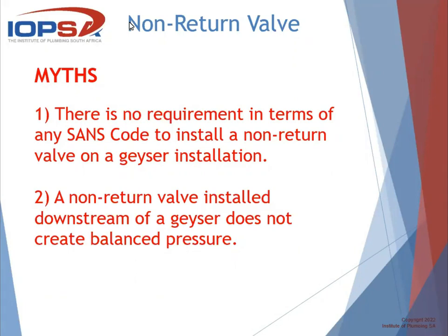So the pump must be able to overcome that non-return valve spring pressure during the day when it is pumping, yes. So you can use spring type valves, but they need to match, or be compatible with the pump. I've seen many spring type valves used and it works perfectly well.